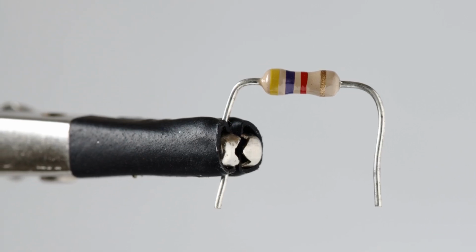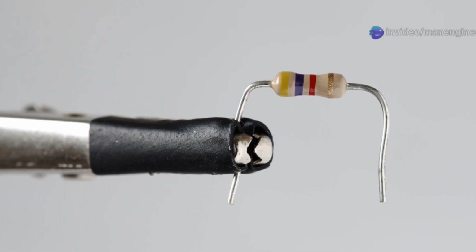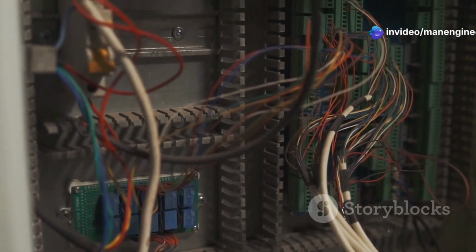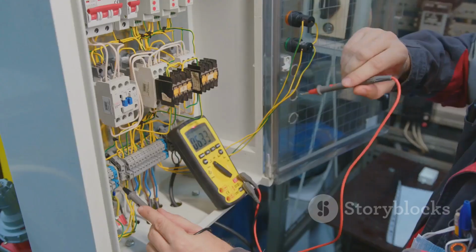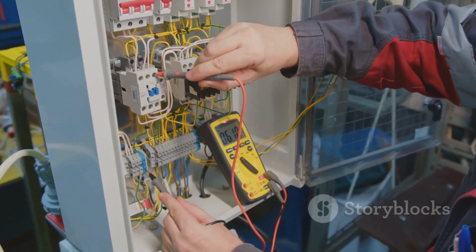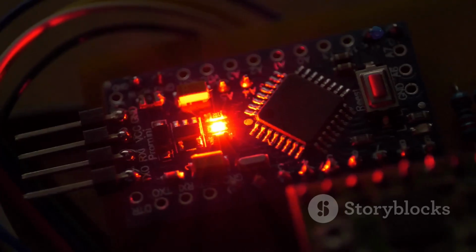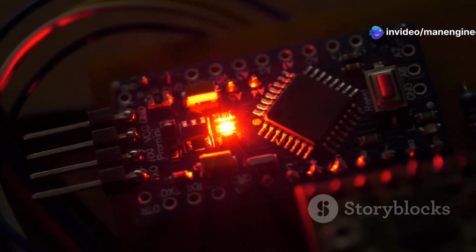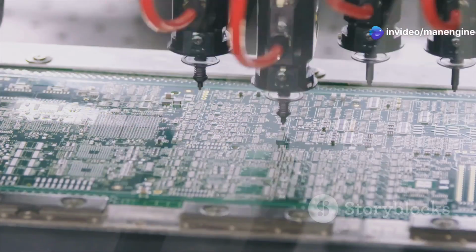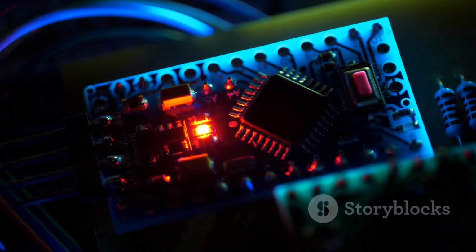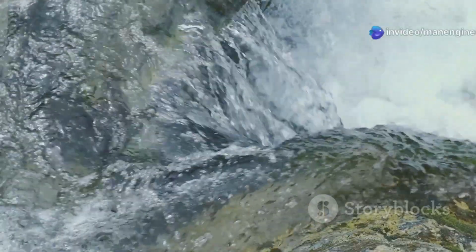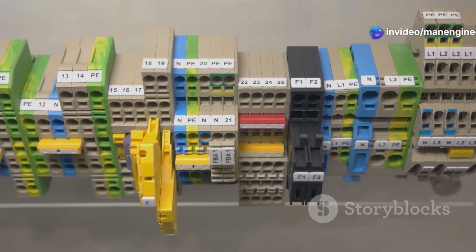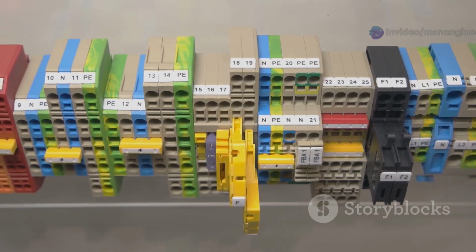Similarly, when resistors are connected in parallel, we observe current division. The total current flowing from the source towards the parallel combination will split and flow through the different parallel branches. Each branch will carry a portion of the total current, and how much current each branch gets is inversely proportional to its resistance. This means a path with lower resistance will attract a larger share of the current, while a path with higher resistance will see less current. Current, much like water flowing downhill, tends to choose the path of least resistance. This current division principle helps us predict how current distributes itself in parallel configurations.